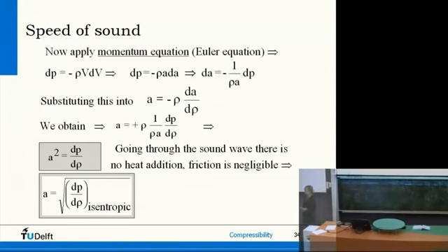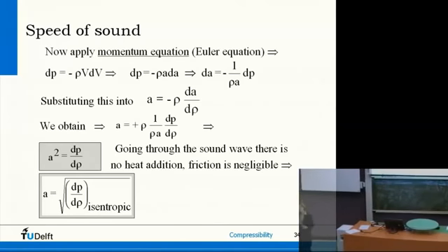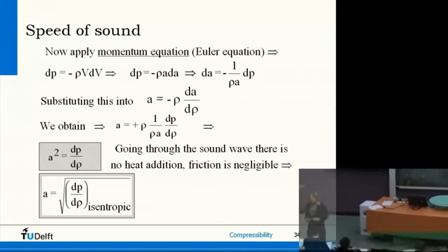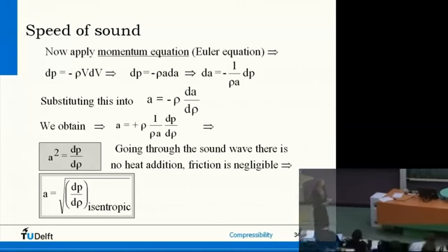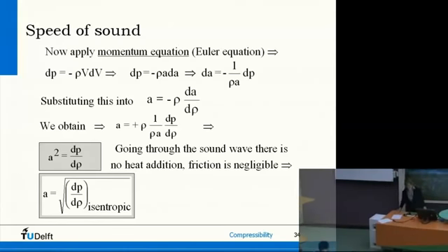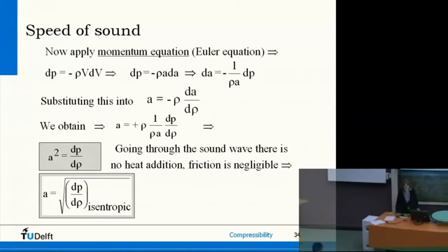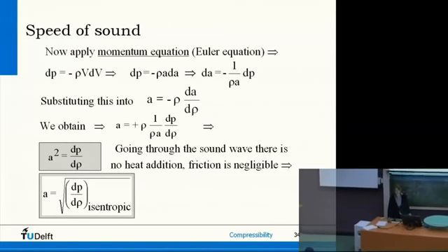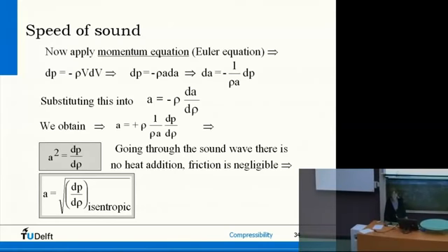What I'm going to show you is that speed of sound is related to pressure and density changes, and I use my good old friend the Euler equation in here to get the pressures in. I won't ask this derivation at the exam. dP is minus rho v dv, Euler. Velocity is now speed of sound, A. So I have this Euler relation saying changes in pressure are equal to minus rho A times changes in speed of sound. So my speed of sound change dA is equal to minus 1 over rho A dP. I had this already from the mass conservation.